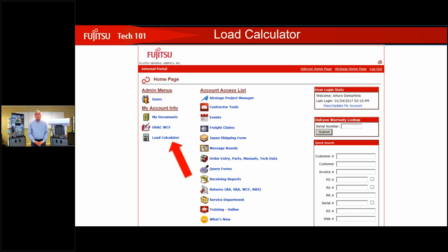All right. So if I'm doing hydronics, I'm doing a heat loss. If I'm doing heat pumps, I'm doing a heat loss and a heat gain. Nobody can walk into a building and just because they've got 30 years experience, puff out their chest and say, yeah, feels like 4 tons. No, can't do that. Now, a lot of you guys do block loads, which gets you a number that you can then bid the job.